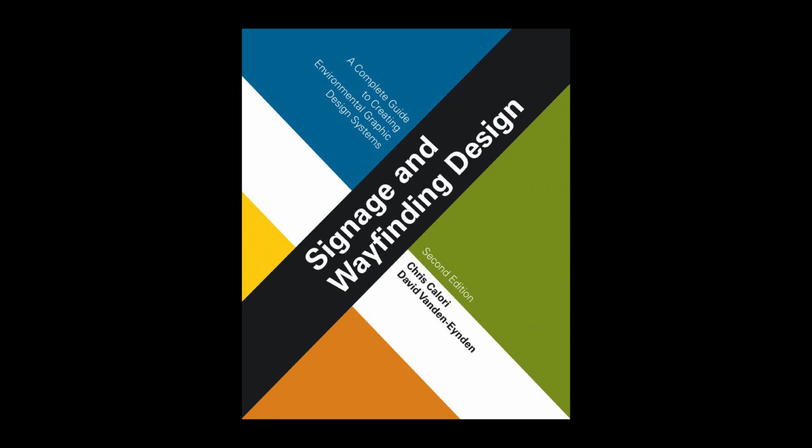In signs with porcelain enamel coatings, the graphics are typically fused into the coating, rather than being applied later by a different process, resulting in very durable, surface-integrated graphics. For this reason, porcelain enamel is an ideal coating for signs in high-wear environments, such as subway stations and exterior exhibits. In fact, the porcelain enamel signs of the London Underground are so emblematic of that system that miniature enameled signs are sold as souvenirs of London.